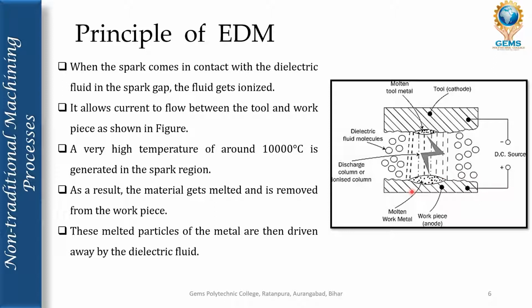As a result of this high temperature, the material gets melted and is removed from the workpiece. These melted particles of metal are then driven away by the dielectric fluid, so that we get the desired shape.